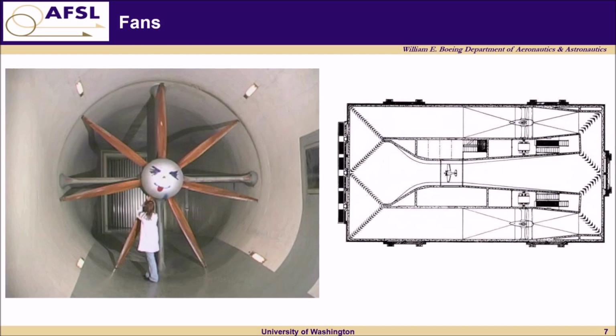And as you can see from the diagram on the right, there are 2 mirror image sets of motors and fans. As the video mentioned, each fan is powered by a 500 horsepower DC electric motor, and the fan motor armatures are linked by an idler shaft to ensure that both fans spin at the same RPM. Okay, enough of my commentary. Let's jump back to the videos.